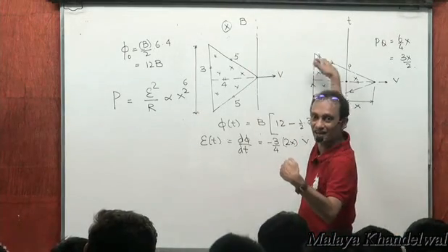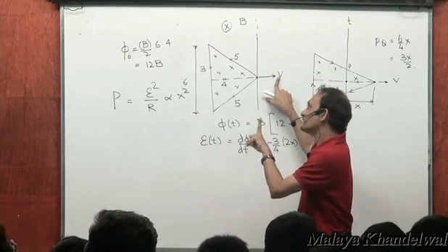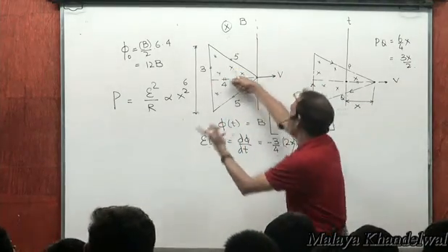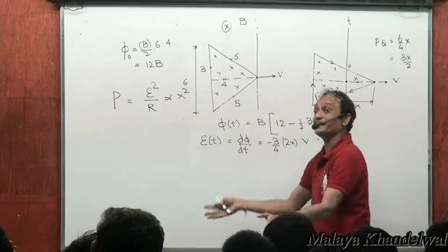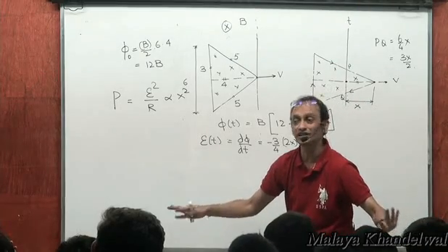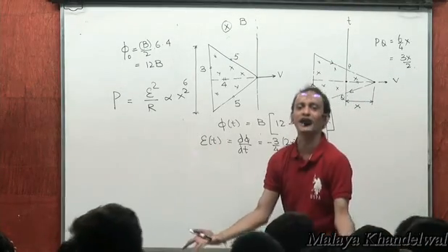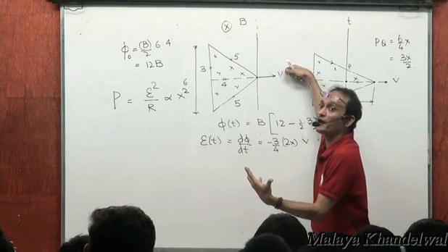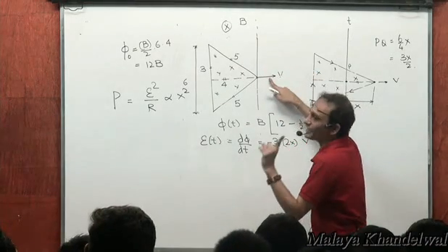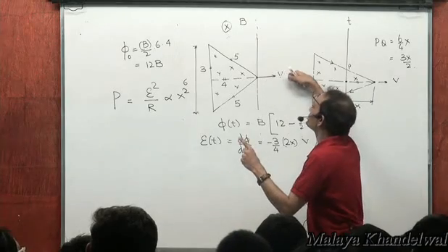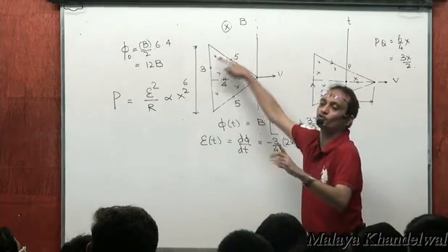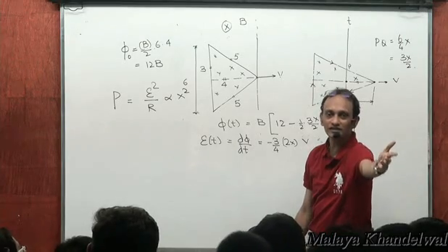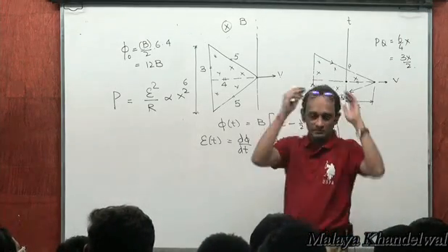You know what I'm saying? So that's the job of the external agent. It prevents the kinetic energy from being consumed as thermal energy. If you leave it and let go, then kinetic energy gets consumed as thermal energy, and therefore kinetic energy depletes and will die down. But if you apply a force, then that force will provide enough power so that kinetic energy is not touched. The power that this provides gets consumed in Joule heating. You understand the energy implications of this? Hopefully. Right?